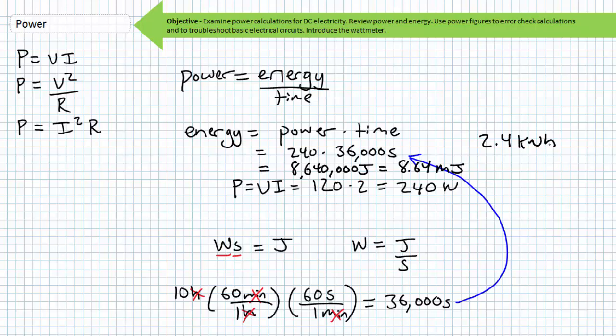Energy is power times time. 750 watts used for 1 hour is 750 watt hours. In terms of kilowatt hours, the common unit of energy used by your electrical utility, we have to move the decimal place over. So it's 0.75 kilowatt hours of energy.